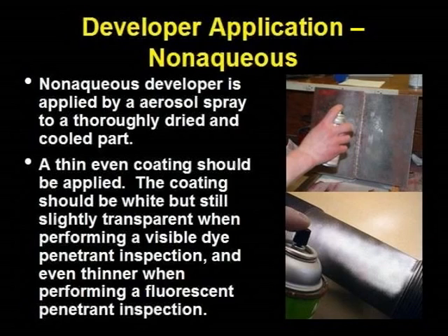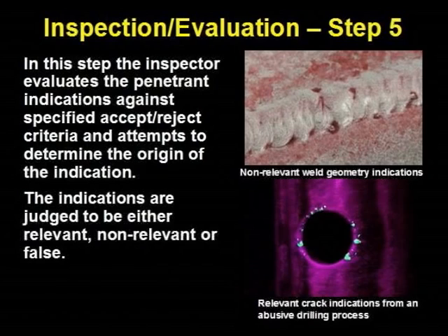Non-aqueous developer may be used with both visible dye and fluorescent penetrants. The developer is applied by aerosol spray to a thoroughly dry and cool part. The coating should be thin, white, and slightly transparent.